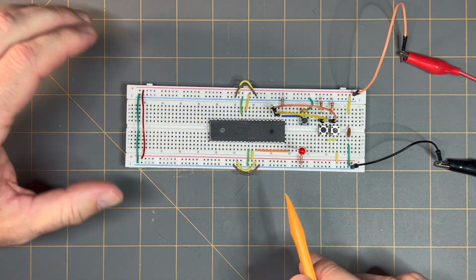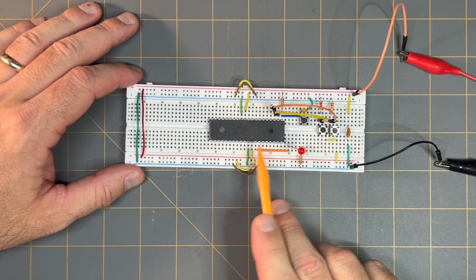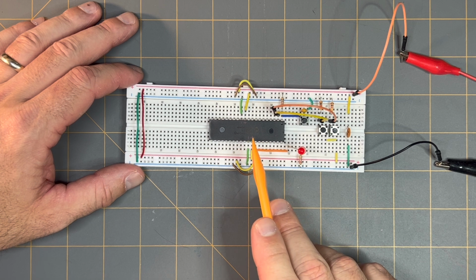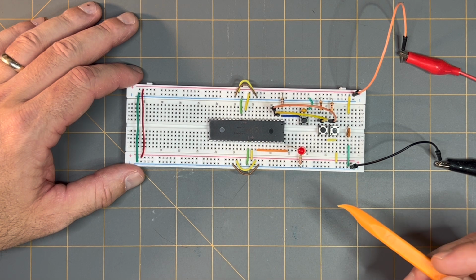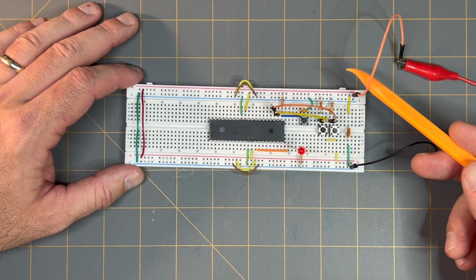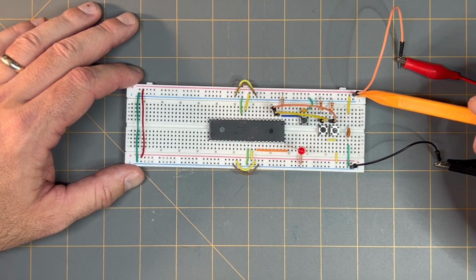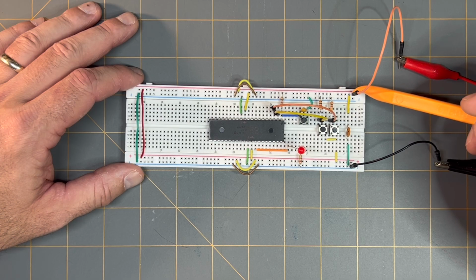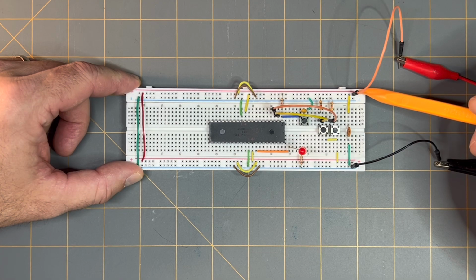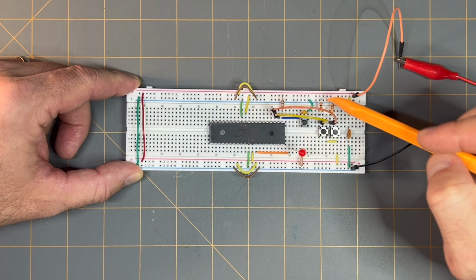So to make the proper connections for power for the PIC 18F4525 and all the other components that it'll drive, I first started with where the 5-volt power supply will come in to the breadboard. I started with this orange jumper wire, and I placed it at the top point, on what I'm considering the left-hand side of the board, in the first point for the positive power rail on this side of the board.